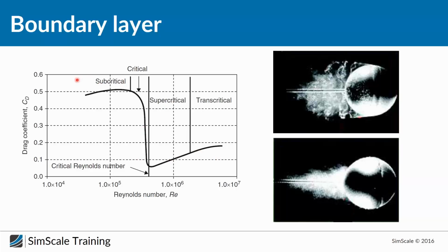First of all, that sounds strange because when you remember the first slide, you saw that the drag was higher. And now again, it's very important to understand these two components of drag. For a laminar state, the viscous drag or the skin friction is way lower. But the pressure-induced drag, because of the flow separation, which is sucking back the ball, is much higher.